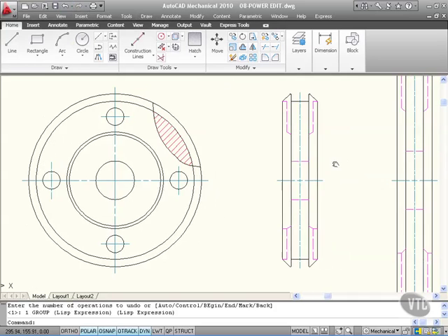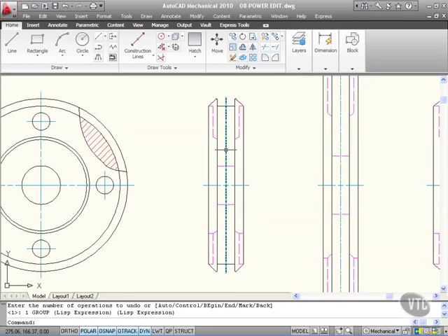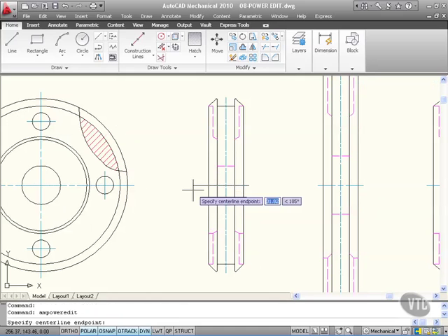Let's just pan across here now and look at a regular center line here. There's one there and there's one there. I'll hover over the end here and double click. I can now specify a centerline endpoint. Look, can you see I'm taking that centerline further out there by moving it freehand? So if I take that way and type in 50 and press enter, that centerline extends outwards by 50 along to the left, the direction I was moving it in. Only this end has changed.